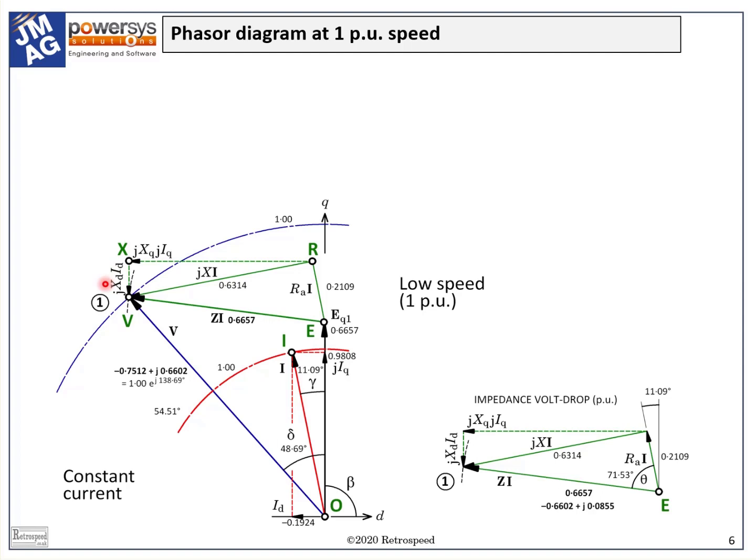Xd and Xq are equal, but in the IPM or any salient pole synchronous machine, they are in general unequal. With separate components, the diagram is set up ready to deal with the salient pole machine without any change in its form, only in the values of the reactances Xd and Xq. This form of the phasor diagram of the synchronous machine dates back to the celebrated French engineer André Blondel about 1895, and it has been used continuously since Blondel first published it.